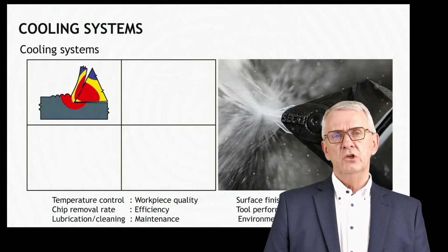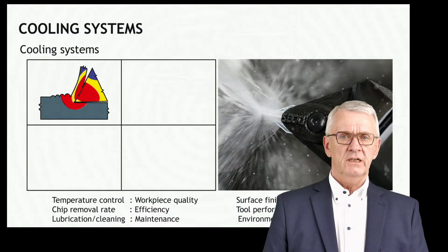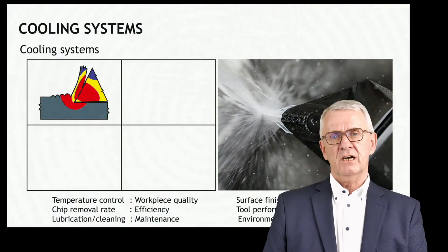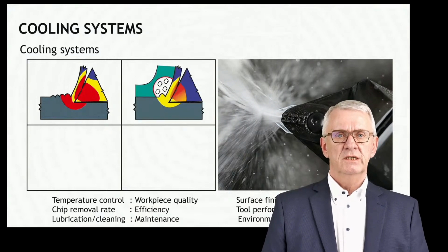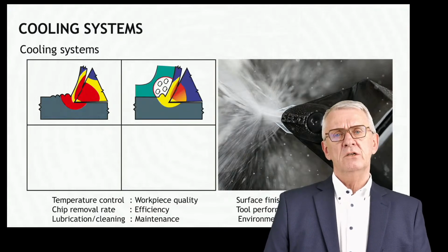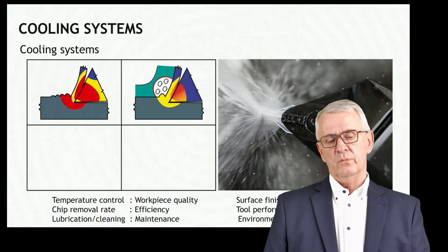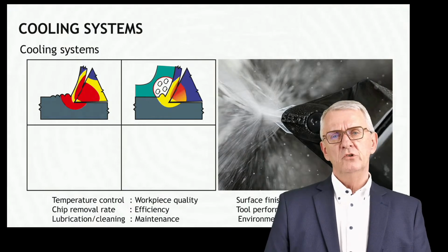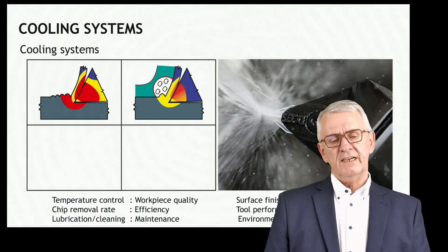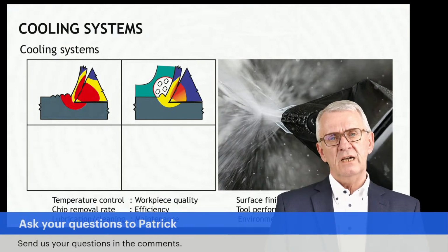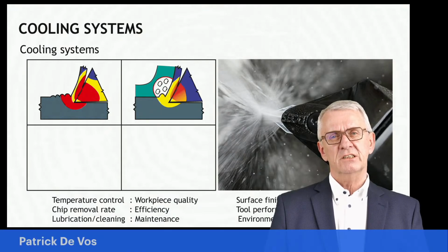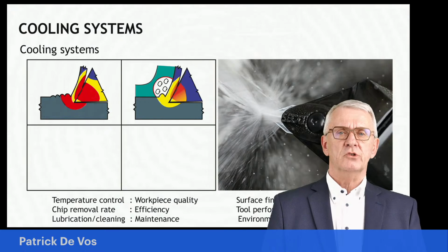I start with no cooling, the so-called dry machining. Dry machining is machining where I do not apply cooling. And we saw that in such a case, heat develops, heat spreads out, heat leads to different types of temperatures. Today, and historically, we use mostly what is referred to as emulsion cooling. To do effective cooling, you should be able to put the cooling where the heat is generated, on the cutting edge, where the material actually is deformed, but that's physically impossible.